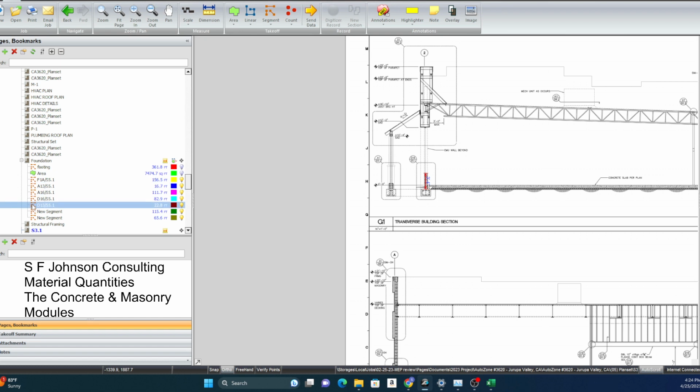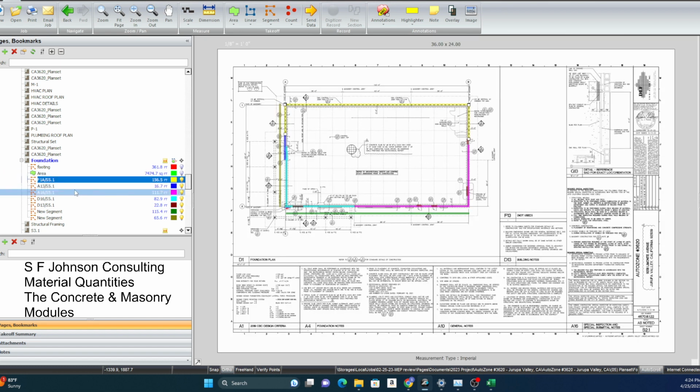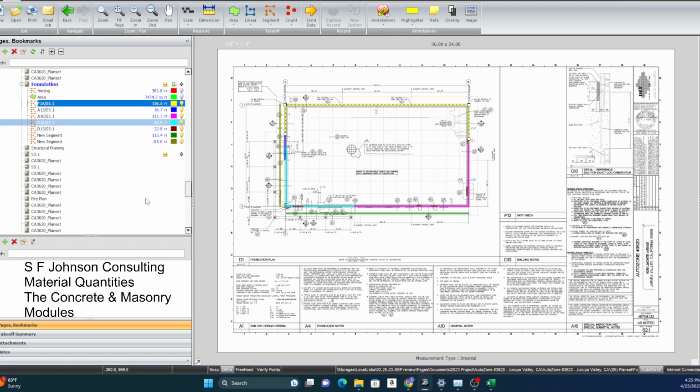And our length of that F1A, we had 157 feet. If it's a 2x2 block, that's your 2 dimensions, that's 4. And then by the length, 157, that's your cubic feet. Divide by 27. That's how many cubic yards of concrete you need for that little F1A stretch.